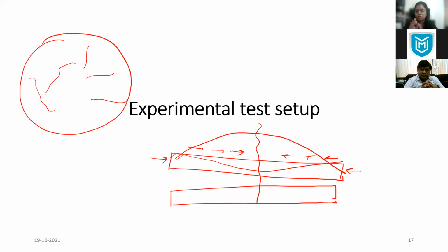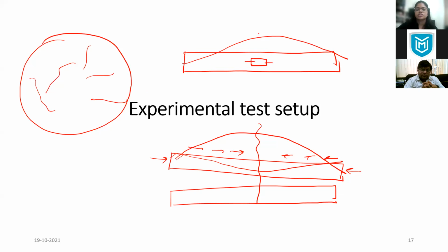Although I used optical fiber distributed throughout the specimen, there are some papers in which they made these shrinkage molds and used point sensors. They placed the sensor only at the center, because they know the crack is going to occur only at the center of the specimen. You can record it.